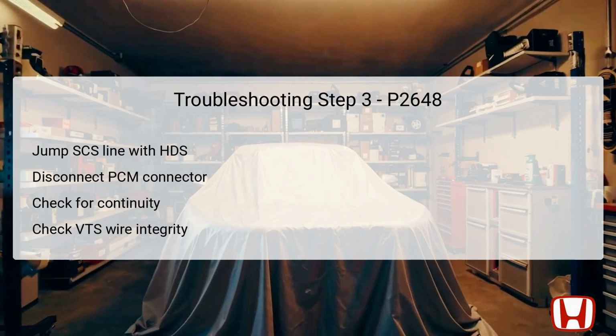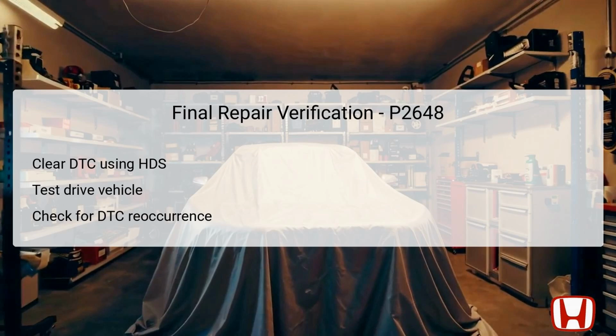In such a case, the next step would be to update the PCM software if it is not up to date, or consider substituting it with a known good PCM before rechecking for the DTC P2648. Once the necessary repairs or replacements have been completed, it is crucial to verify that the work was successful in addressing DTC P2648. Begin by clearing the diagnostic trouble codes using the HDS to reset the system and allow the vehicle electronics to function anew.